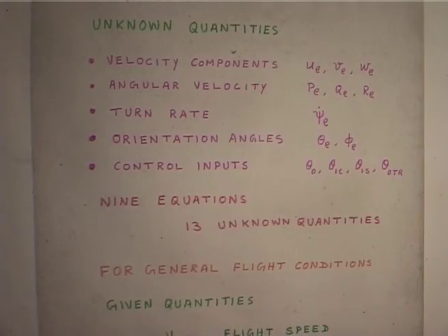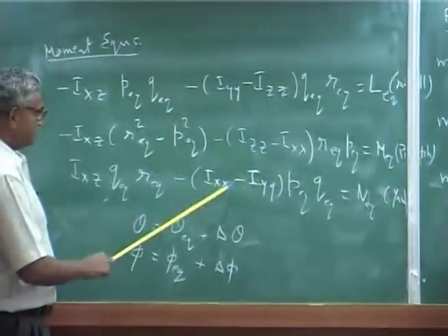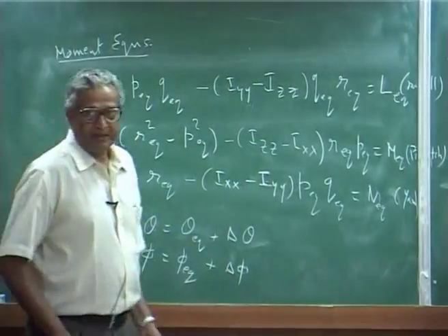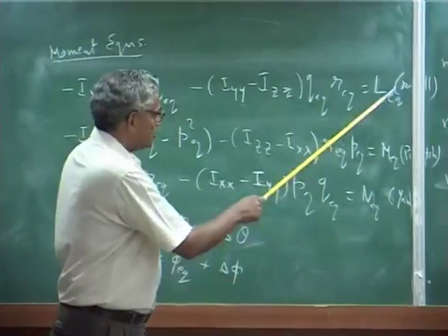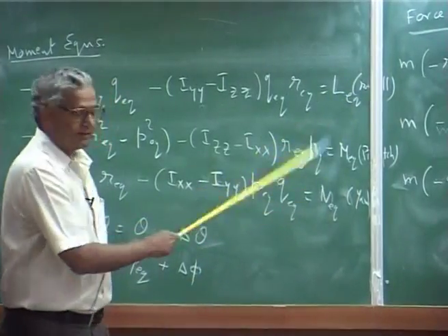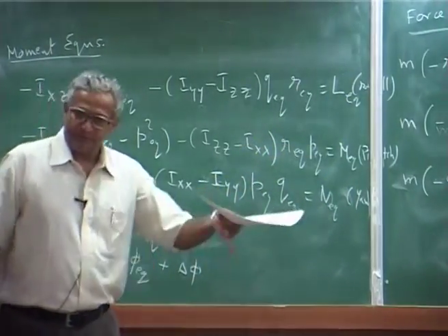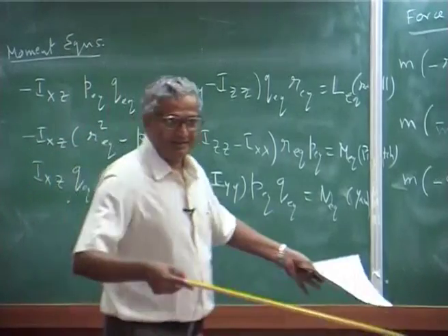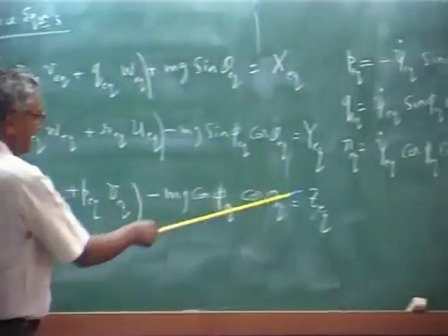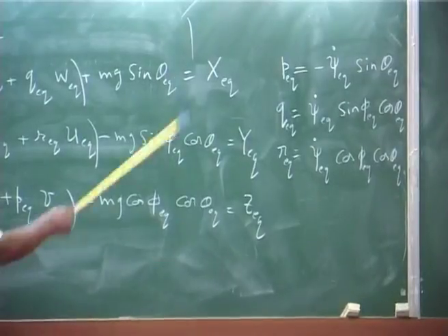Please note that, that is very important: I know the mass of the helicopter, I know the inertia properties, the tensor. External loads, these are my rotor loads and fuselage aerodynamic loads, any horizontal surface, any lifting surface, everything, they provide those loads here.